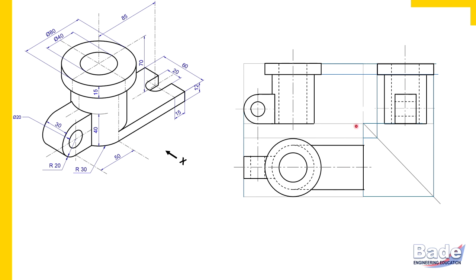Otherwise, in the front view, it is simply a rectangular strip. So draw end projectors, the right end of the plate and the left end of the plate. Now the left end of the plate is where that plate meets the cylindrical surface. So here. From this point where right now this red spot is, and this point we should draw end projectors. So this is how these end projectors go.